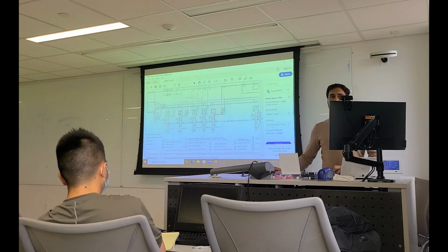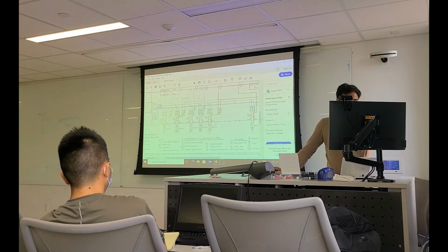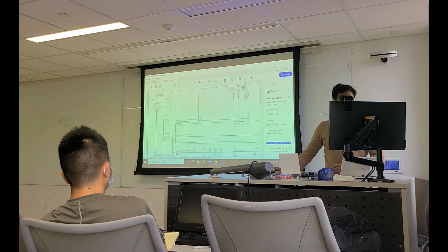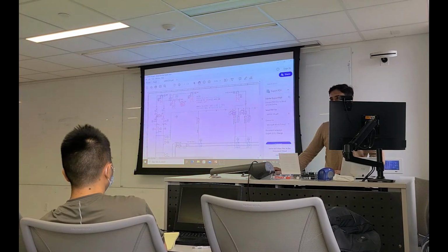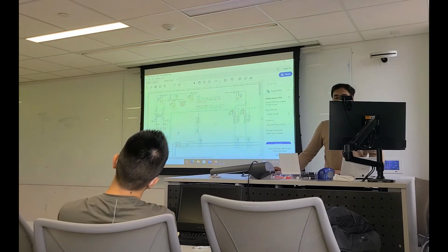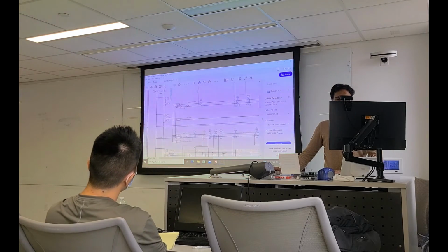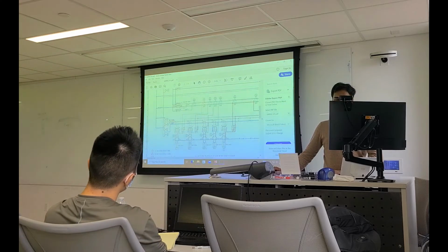Yeah. Anyway, so this is TMGa 1, 2. Don't focus on these values. So what we do, we flow the gas. So here you can flow argon, you can flow nitrogen, you can flow hydrogen, whatever you want. You have your valves, you have your MFCs, and you can decide which gas should go inside the bubbler.